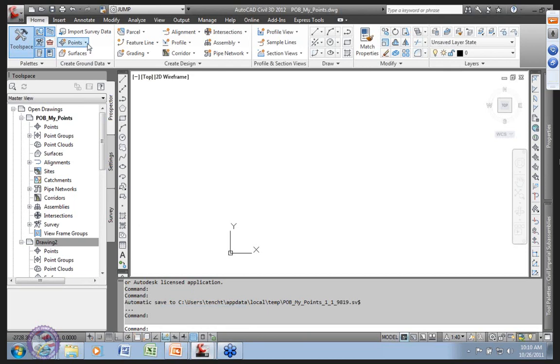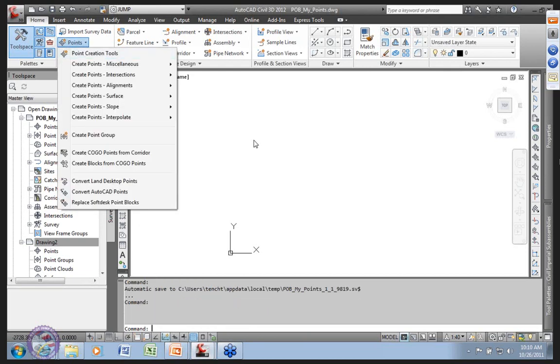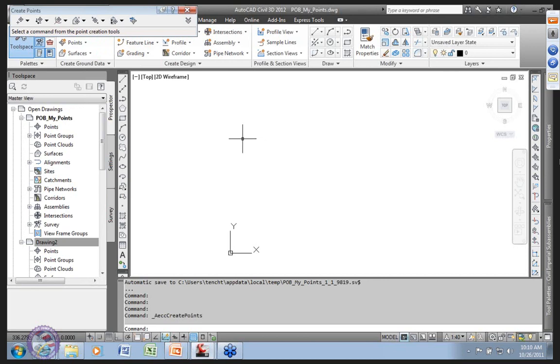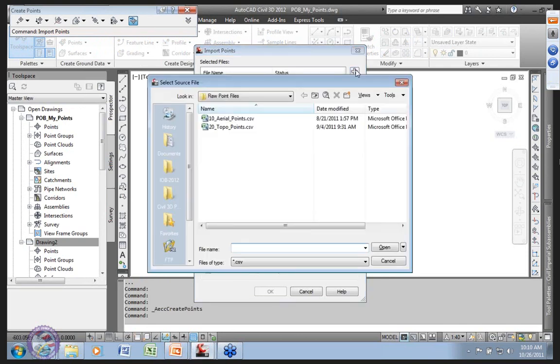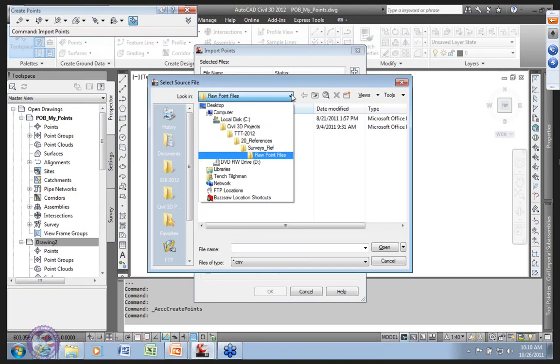Fundamentally, though, we have ways of bringing in points. One of the classic ways is, hey, I have a point file out there. So we bring up the points toolbar, right? And in 11 and 12, you get this nifty box, and we say, hey, we want to go out and grab points, and I have publish points and publish point data, and that is an extremely important little idea in Civil 3D. You're always working towards, what am I really going to publish, instead of, I'm going to give them everything and let them deal with it.